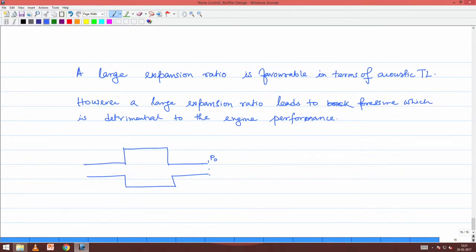So, you have exactly the atmospheric pressure. As you know from principles of fluid mechanics, when you have a mean flow through a pipe, because of the viscosities in the flow situation, there will be a pressure drop as the flow happens through the pipe, right, which means the pressure at each progressive station would be higher. So, P1 must be higher than P0, only then is the mean flow going to happen, otherwise the mean flow cannot happen.